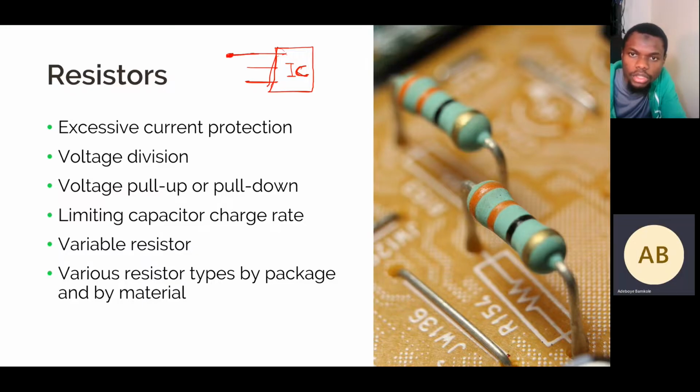If you don't connect anything to this pin, the pin is floating. Let's say it's an input pin, you set it as an input pin. As this pin is floating and you don't have anything connected, it can pick up stray charges from outside.